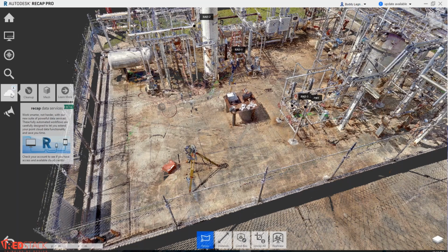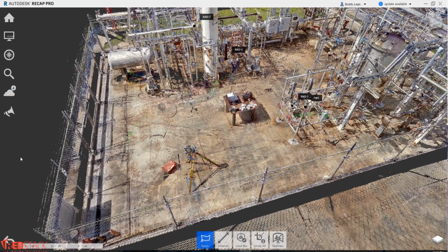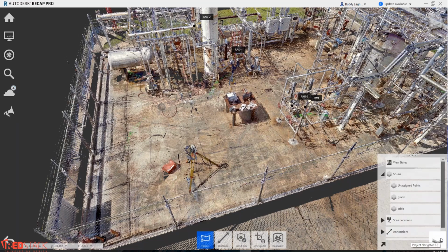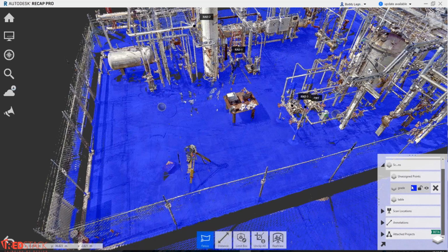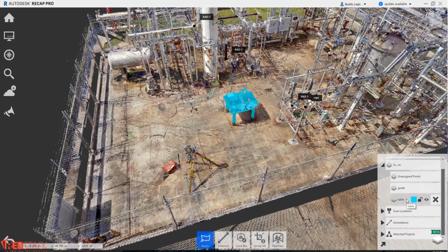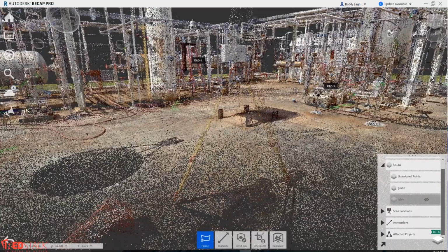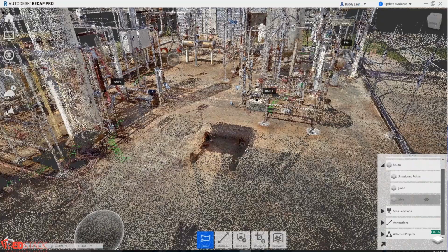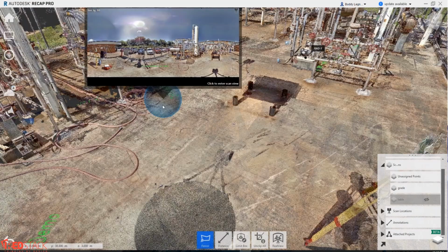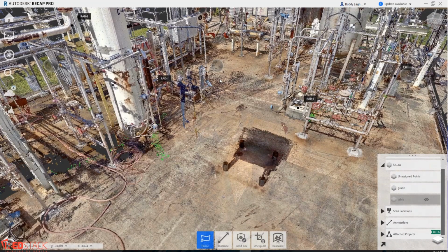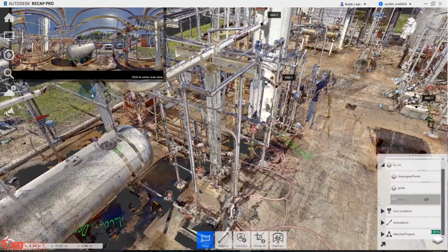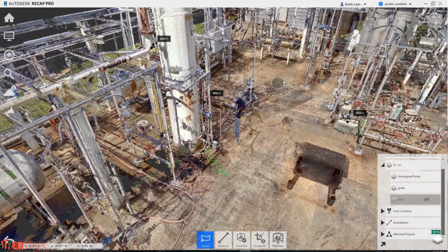If I go to the project Navigator and look at the layers, you'll see that I've got all my scan regions there. I've got my scans. If I look at some of my existing scan regions, there's that table. It's in a cyan layer. I can turn it off and you'll see it disappear. When I change from a 3D visual view to a bubble view, that's what those disco balls are, and they're scattered throughout the scan. I can change the size of those if I want to make them obvious, and I can turn these things on and off.